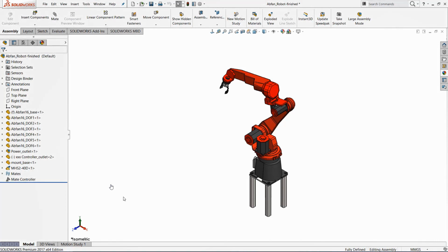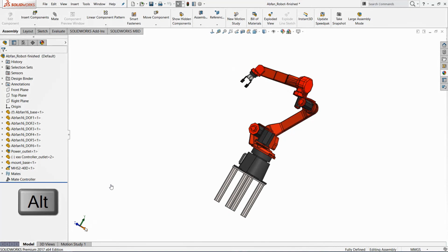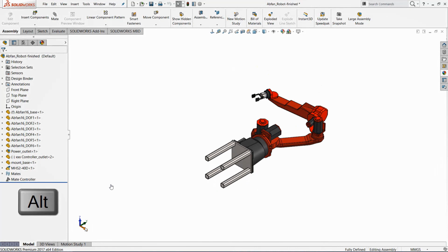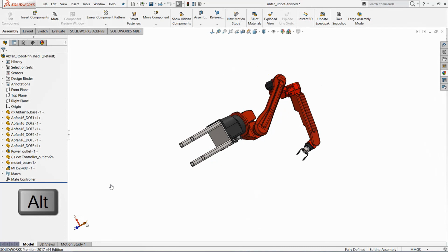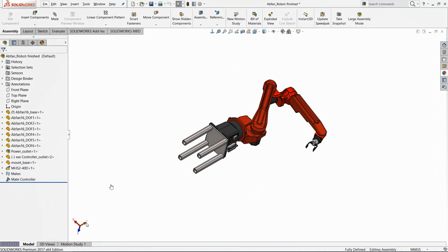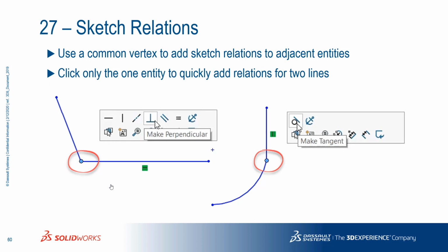And now 15 degrees if I hit the Alt key. So the Alt key does it that way. And if I want to change the direction, I hold the Control key. So it's Control Alt or Control Shift and click those things from the axes from the reference triad, and it will change the direction around. Okay, so there's some functionality there that you guys have.